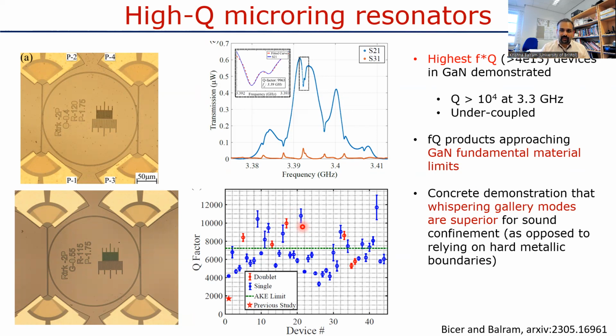But at least one thing that you can take from these results is that the GaN on silicon carbide epitaxy is so good, or the number of threading dislocations at the interface is so few, that we are not able to measure any excess dissipation or scattering of sound. Now, this is an idea that's been well known in integrated photonics, that integrated cavities can get much higher quality factors than bulk resonators. But I believe this is the first time this has been demonstrated in the acoustic domain.